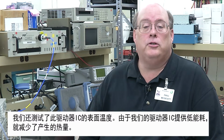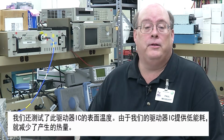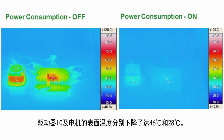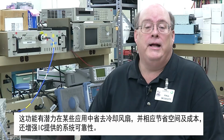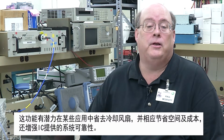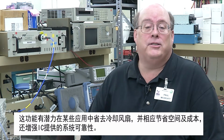We also tested the surface temperature of the driver IC. Since our driver IC realizes low power consumption, it reduces heat generation. As you can see in these images, due to the increased efficiency, the surface temperature of the driver IC and the motor are decreased by up to 46 degrees C and 28 degrees C respectively, with the efficiency feature activated. This feature has the potential to overcome the need for cooling fans in some applications, along with the corresponding space and cost savings and enhanced system reliability that the IC provides.